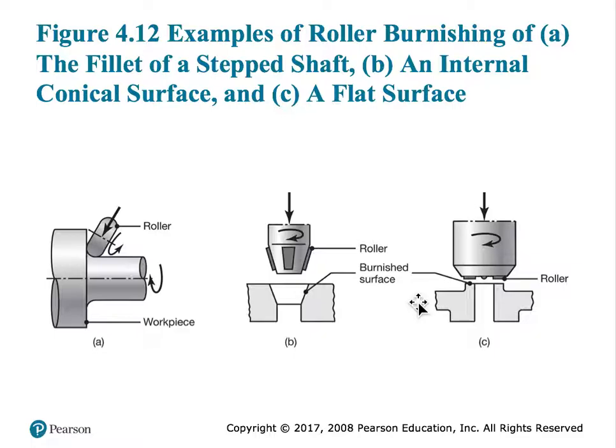But what you will find is that as this workpiece is turning, this roller is held on a rotating chuck, and that chuck will rotate. Sometimes you might even put some kind of sandpaper on that, or there could be individual pieces of sandpaper stuck to the rotating chuck, and that will cause a smoothness on the surface of your final machined piece.